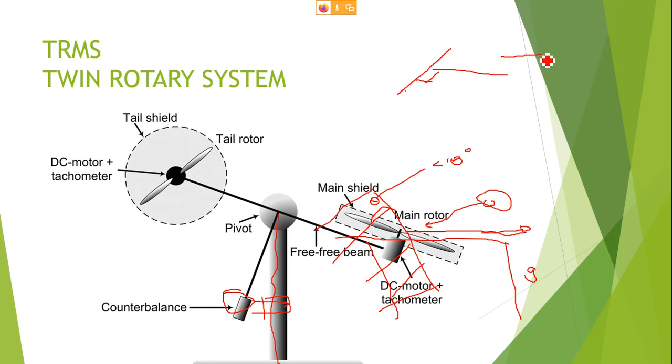For forward motion, the thrust has to be in this direction. For stabilization, the thrust has to be in this direction. In most cases this is exactly 90 degrees. It will not vary much, except in rare combat helicopters. So in most cases, it is 90 degrees.